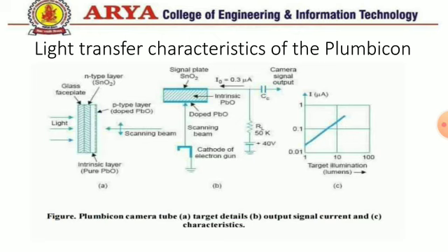It is due to reduction in recombination of electron hole pairs, and that is happening because of the PIN diode, where there is no leaky capacitor, while in the case of Vidicon there is leaky capacitance, which increased recombination of electron hole pairs. In Plumbicon there is capacitance in series, and that will decrease capacitance because of series connection, and that will reduce recombination of electron hole pairs.